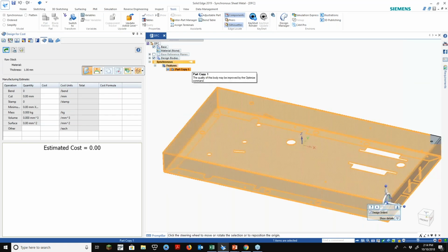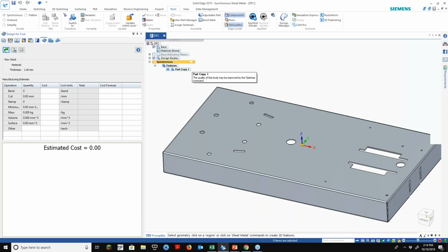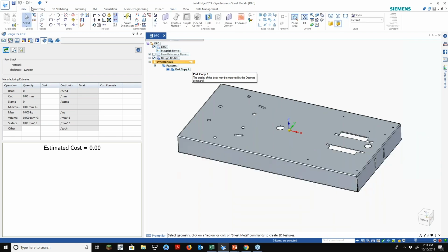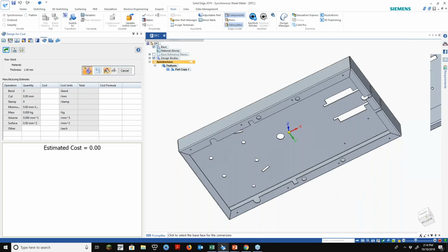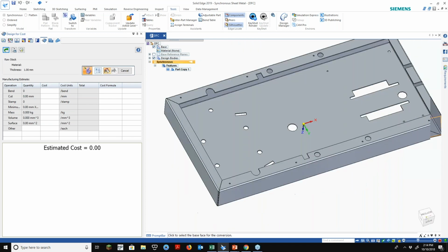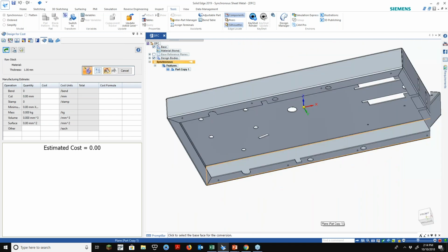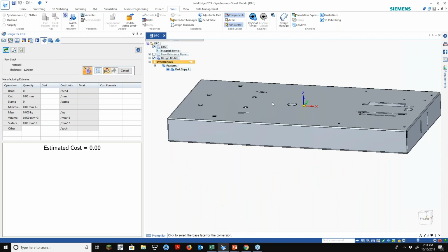So for those who know Solid Edge, we can actually extract some geometry from this. So let's create some flanges and create some tabs. Easy enough to do is thin to sheet metal. So we have a part here. It's got multiple flanges. It's got some complicated tooling to make this particular part, which is an expensive part. But let's go ahead and say this is our tab, and the rest are going to be flanges. So there's going to be several flanges here. That's kind of the first step to make this work.